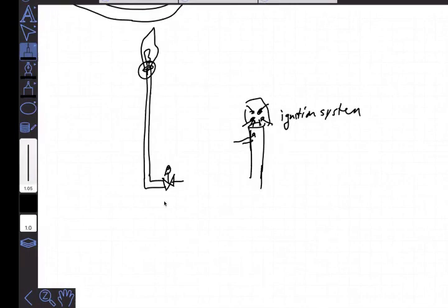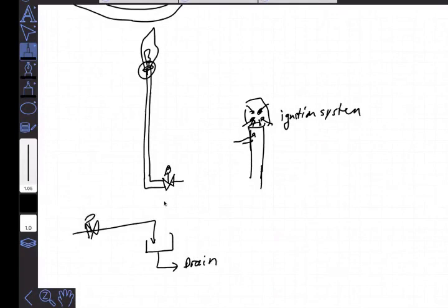You can think of the flare system almost like going to a drain. There are some circumstances under which I will get rid of material and pour it into the drain, right? Now, the flare system is like a drain, but into the air. And so it's undesirable, and people don't like flaring. You shouldn't design it so that you need flaring all the time. It's always better to avoid flaring if you can, but they're also not physical protection, because they are in most cases not completely automated systems.